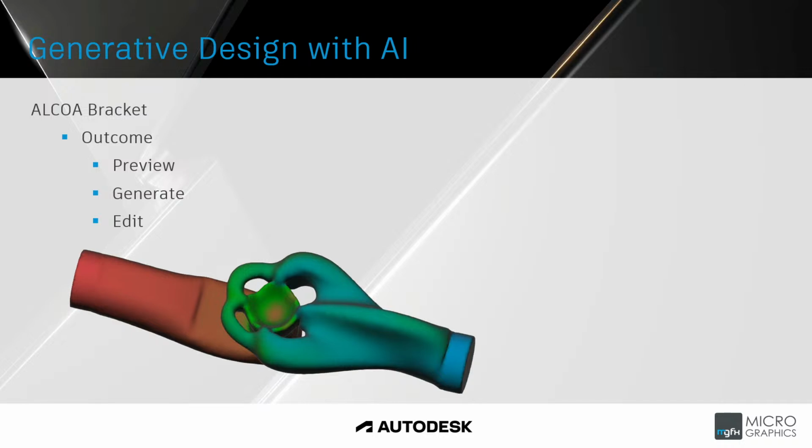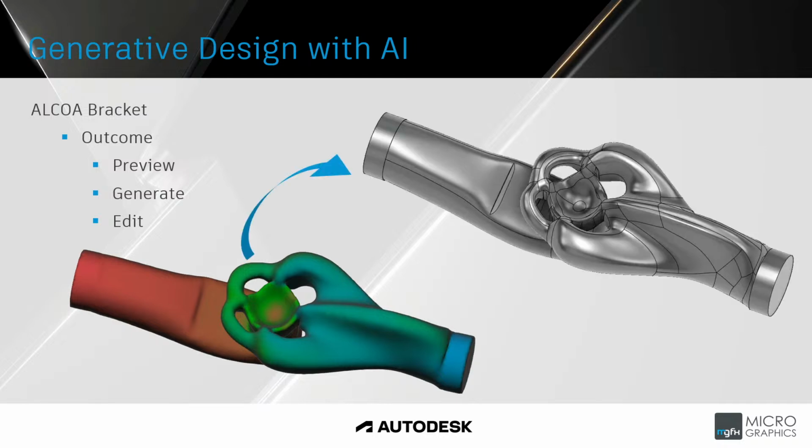But you can see the fluid is no longer following that spherical shape. We see that as the fluid is flowing through the orifice and through the cage that the ball moves up and down in, we can see where the openings of the cage are and how that fluid flows through those openings. If we are happy with this, once again, we can generate that result.